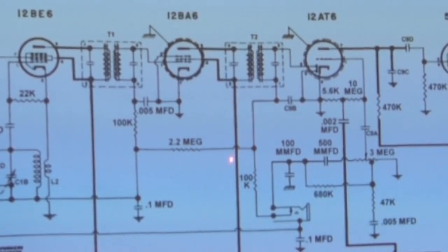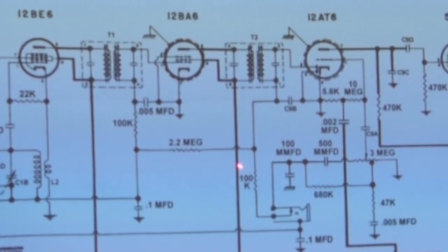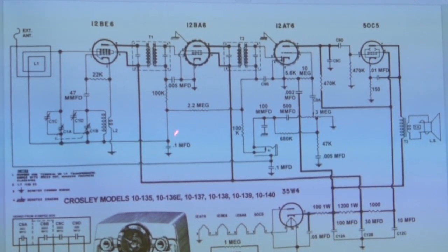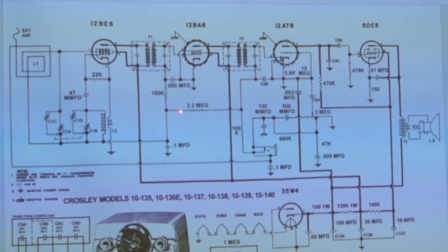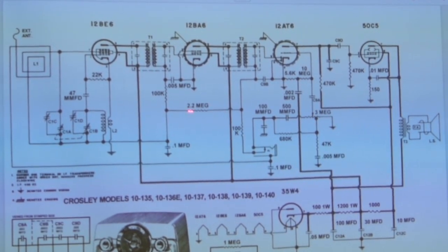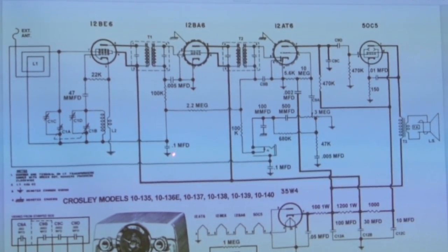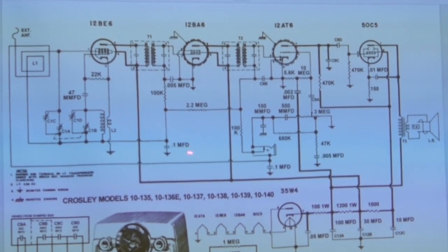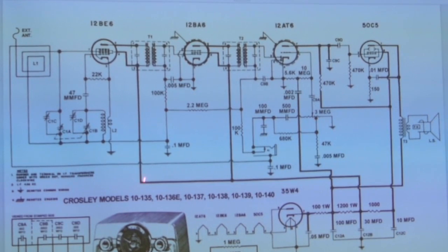You come down here, and now what kind of AVC or AGC problems can you have? Well, this circuit might not be working right. Now here's where you want to get in, and you could use your substitution box if you have it, or at the very least what you should be doing is checking the values, especially in old radios. You know, here's a cap that you'd be maybe wanting to replace, if not all the others. And this represents an RC circuit. So it's a type of filtering circuit which will eliminate or pass to ground the audio portion, the strong audio portion of the signal that you want. And this RC represents a filter that will allow very low frequencies to pass through, but enough that it will track the signal variations coming in and then powering up the automatic volume control circuit.